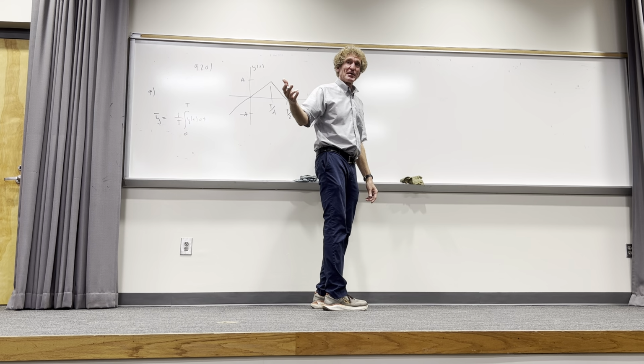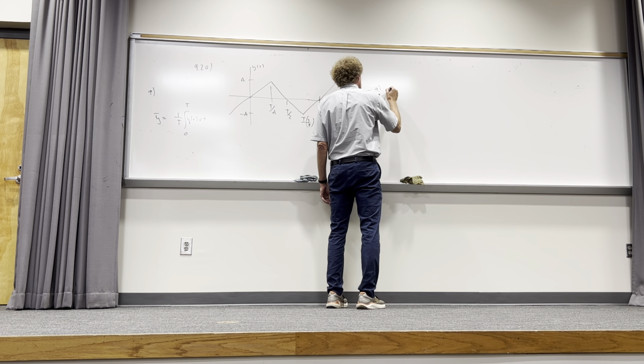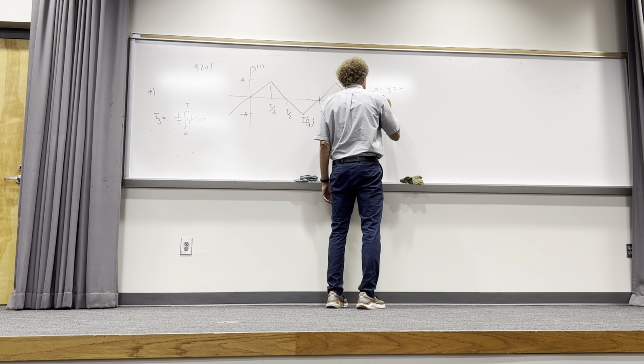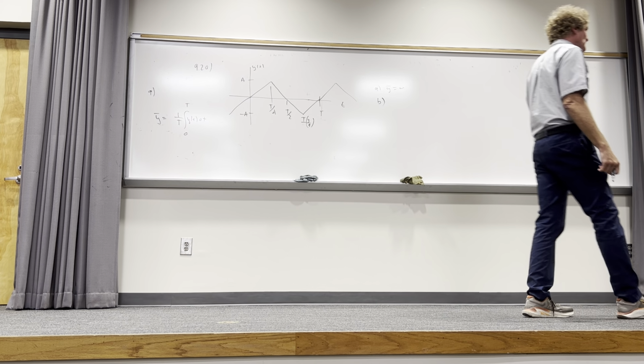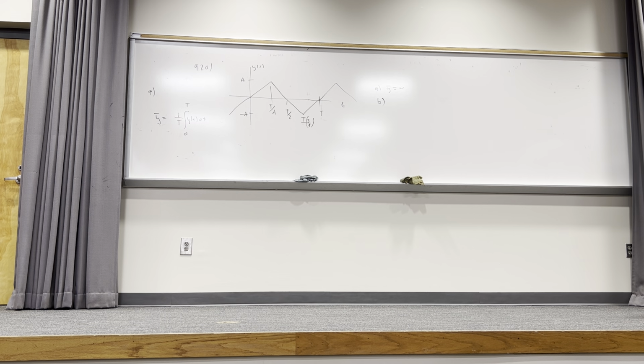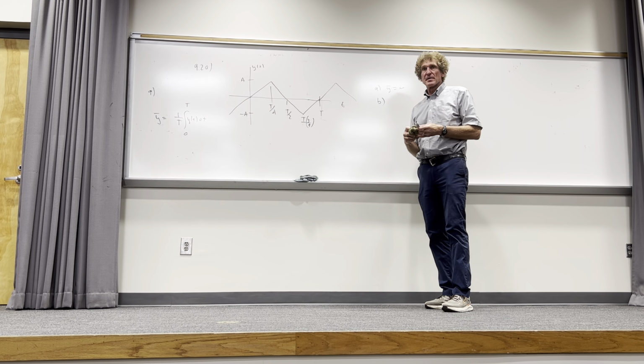Anybody want to help me out here? Isn't that right? Average value is 0. Part A. Y bar equals 0. Now, what's the next part? We're going to do something. So part 2 of this is, if it is half-wave rectified, plot the voltage versus time and determine the DC value. Now this is half-wave rectification, so here's what he means by that statement.